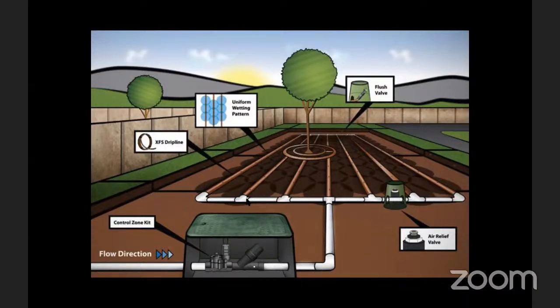And then it goes to the PVC pipe, which gets glued together, has at the T, these T's are glued on two sides, and then the part coming out is threaded. And so screwed into that thread is the adapter that goes to the barb. And you can ask the people at the landscape supply store about all of these different parts to make sure that you get all the right stuff if you have to do the setup. And that allows a greater water flow across this side, which then by the time it goes down to the 1/2-inch pipe, still remains less than the total amount of flow that the 1/2-inch pipe needs.